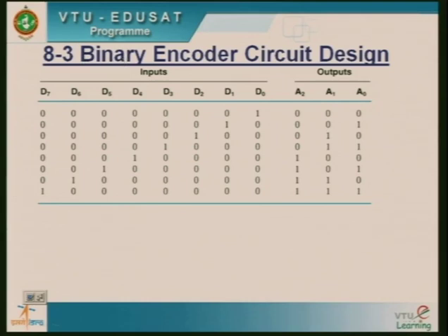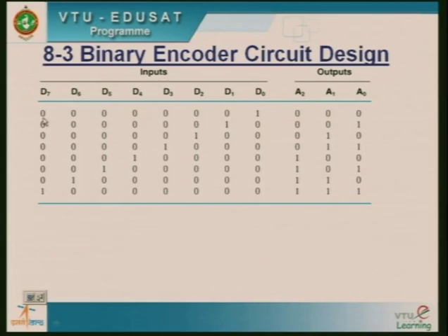Usually in communication circuits, they use combinations of decoder and encoder on the transmitter as well as receiver side. You can see here 8 inputs, 0 to 7. At a time, one of the inputs is high and we will be generating a particular code. So we have 3 outputs, and for a particular input we will be getting a code.